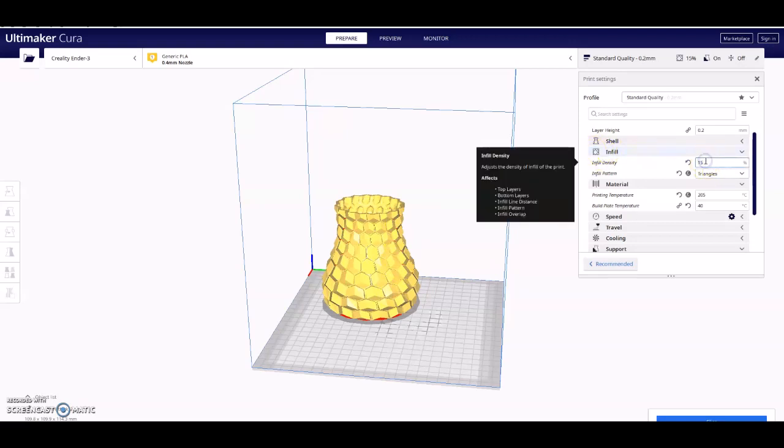Infill, keep this around 10, 15, 20, 25%. I've never seen anybody recommend over 25%. Let's say you're building a box, it's not going to be pure solid plastic. It never is. What happens is it fills a lot of the inside with air. So if these walls are kind of thick, let's say they're an inch thick, that's not an inch thick of plastic. If you cut it, you'll see it shaped like little squares or diamonds.